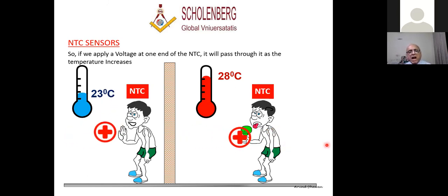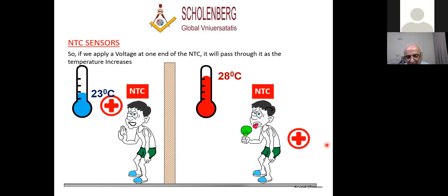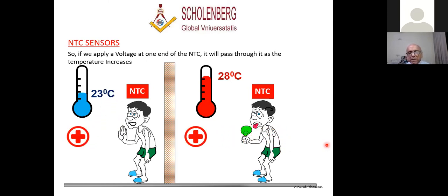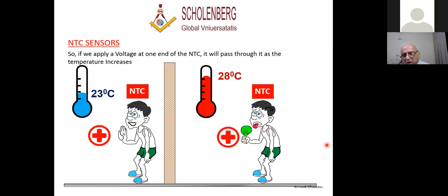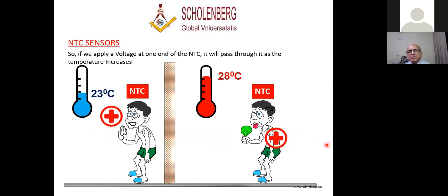In all our air conditioning applications, we use NTC sensors. NTC means that the resistance decreases when the temperature increases. So if the room temperature increases, we will switch on or operate the controller, whatever it may be as the case may be. Okay. I hope that is simple and well understood.